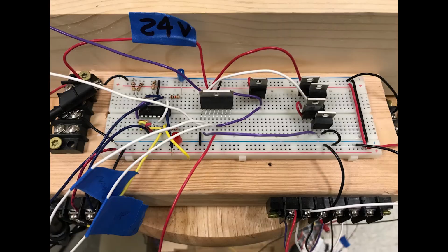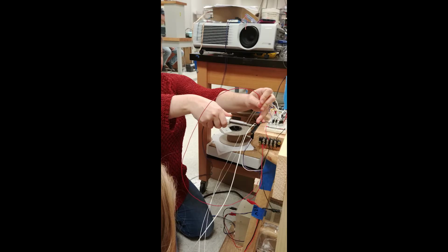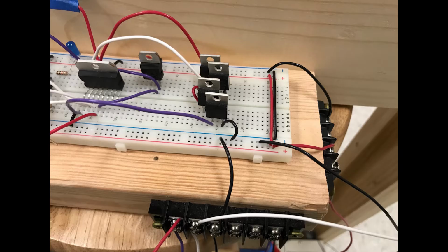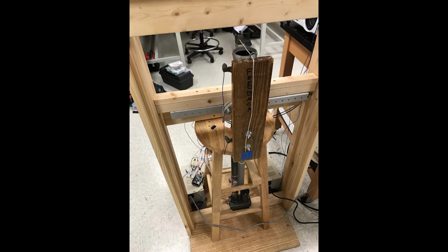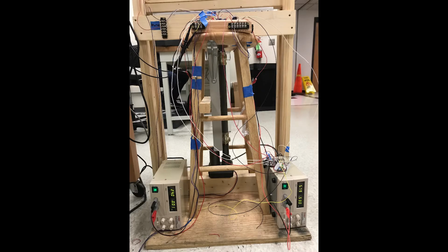Next, we took the system that we had created and combined it with parts of the existing analog system that was already connected to the window. We replaced the analog input signals with our mbed and Photon, and then took our up and down digital output signals and put those into the H-bridge that was already set up with the higher voltage for the motor. We also took the power supplies that were already part of this system and used them to power our devices.